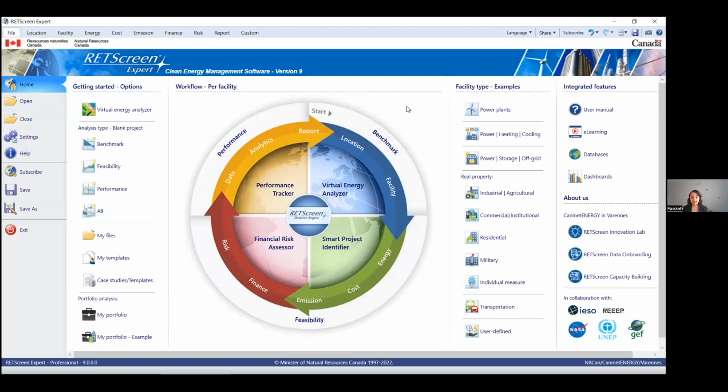That's why we call these deep retrofit archetypes intelligent, because as soon as you choose your location and you click on calculate, the archetype is going to first adjust the heating and cooling load of your building based on the location that you chose. This is what is already being done by the other archetypes, the 30-40% energy reduction versions. Second, they are going to electrify the proposed case heating system. They will choose between 3 different technologies: electric boiler, air source heat pump, and ground source heat pump.